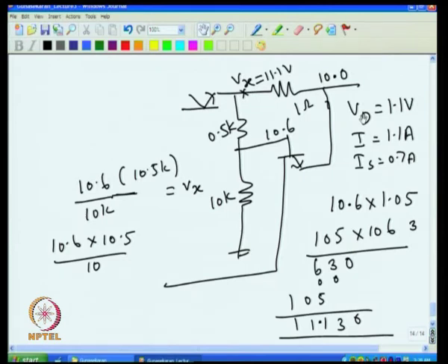You work out for different resistances, you will get the idea of how to reduce the current under short circuit condition. But actually, the basic principle of working is like this: the voltage that is there across this resistor under normal working, because in normal working condition you have 10 volt and that 10 volt also will be reflected here. That 10 volt is divided between these two resistors. So, there is some voltage drop across this under normal working condition, that is working as a reverse bias for this,